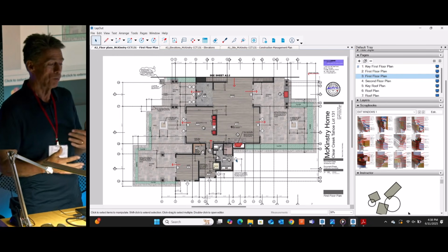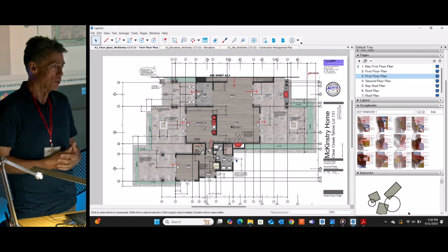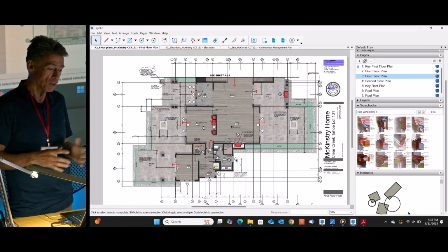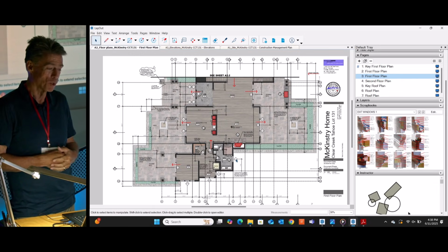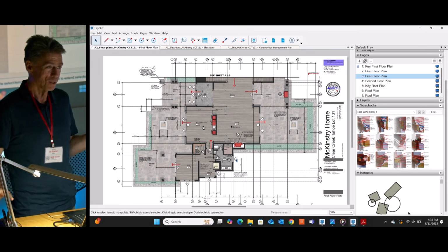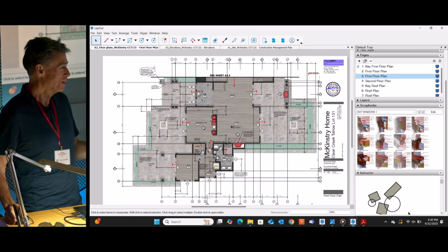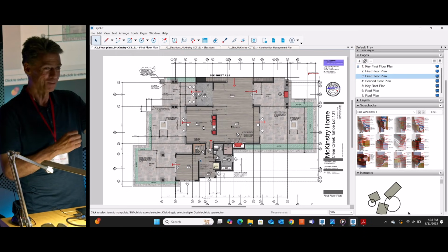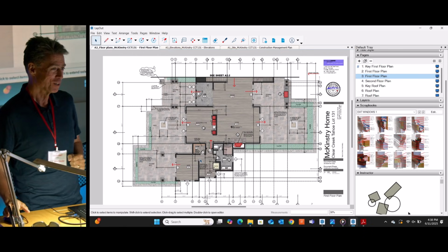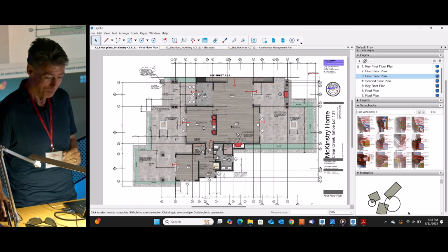The only difficult part is keeping track of the grid lines, because I do put grid lines for every single corner and element of the entire home. So a lot of times we go past Z up to 26, 30, you know, so that can be kind of a hassle if you accidentally put two grid lines with the same letter and they're off by 5.5 inches because one's catching one side of the stud, one's catching the other. It's happened to me before.